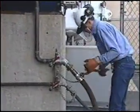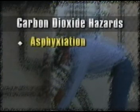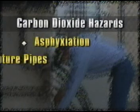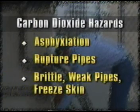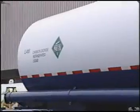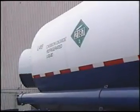When working with carbon dioxide, you need to guard against three possible hazards. First, carbon dioxide can cause asphyxiation by reducing oxygen concentration in the air. Second, carbon dioxide can cause high pressure and rupture pipelines. And third, carbon dioxide's extreme low temperature can also make metal brittle, weaken pipes and lines, and freeze human skin. But by following specific guidelines, carbon dioxide can be used safely and effectively.